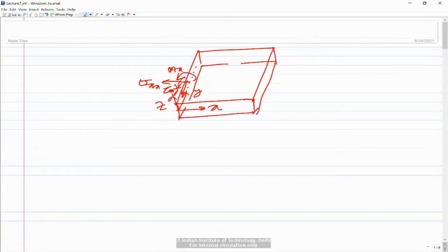So on the negative x face, the moment resultant mx would be about the negative y-axis, and mxy would be the moment about the positive x-axis. So like that, based on the positive sign convention for sigma xx and tau xy. So is that clear?